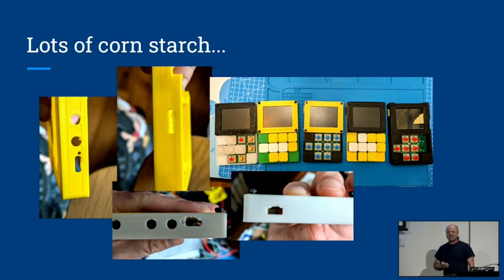I thought people would like to see just pretty pictures of things, or maybe not so pretty pictures of things. So when I talk about 3D printing, I have done a lot of 3D printing in the last 12 months, because even something that looks as simple as the picoTracker, this little fairly rectangular case, turns out there's a lot of things that can go wrong, especially when you're printing little cutouts for power buttons and USB. There's more examples of the SD card slot not being right. Here's some of the different variations I tried printing. This one is actually a contribution that we got from one of our early adopters. So a lot of 3D printing involved.